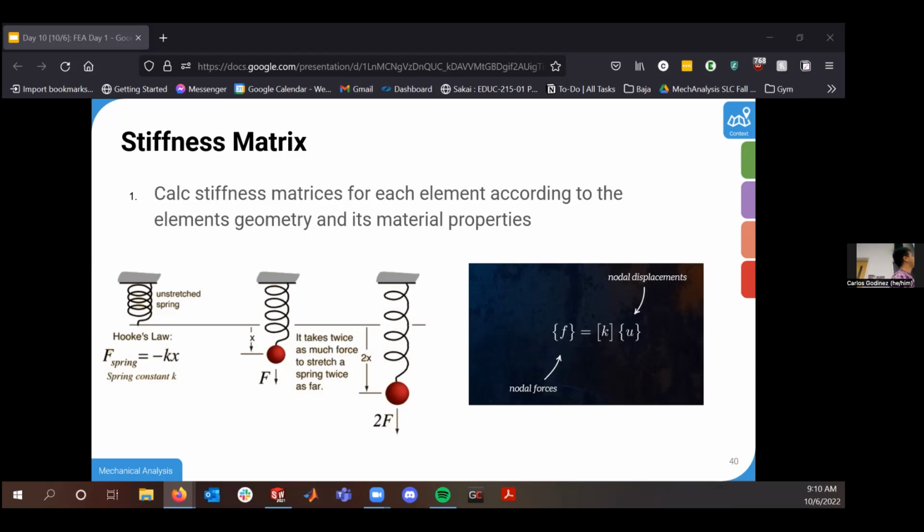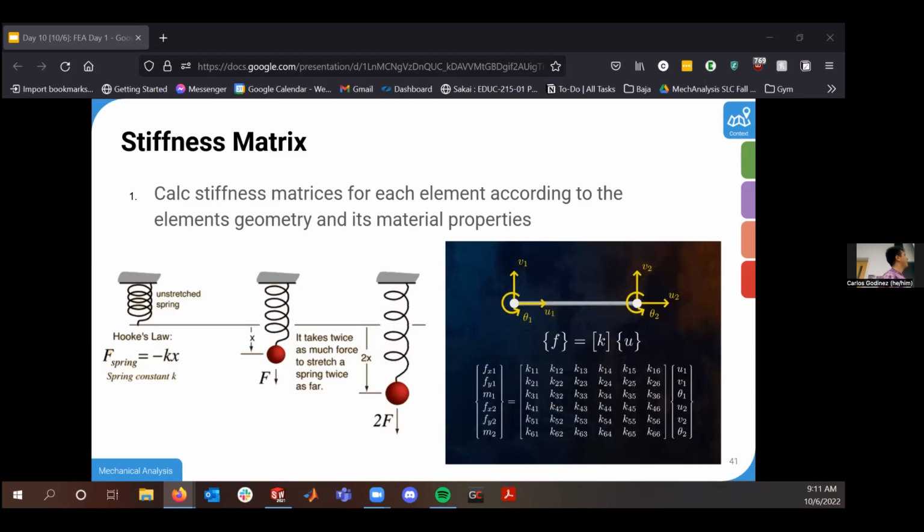and some stiffness matrix. What does that stiffness matrix actually look like? For each one of those individual degrees of freedom, I now have an approximate stiffness constant depending on material properties and geometry, for each one of these directions.